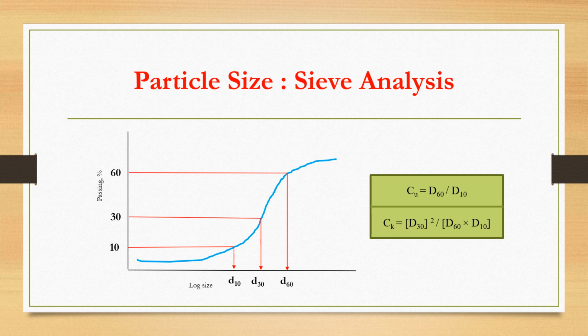Additionally, results of grading tests can also be tabulated using geometric properties of the grading curve. These properties are called grading characteristics. First of all, 3 points are located on the grading curve, namely D10, D30 and D60. For example, D10 means the maximum size of the smallest 10% of the sample.